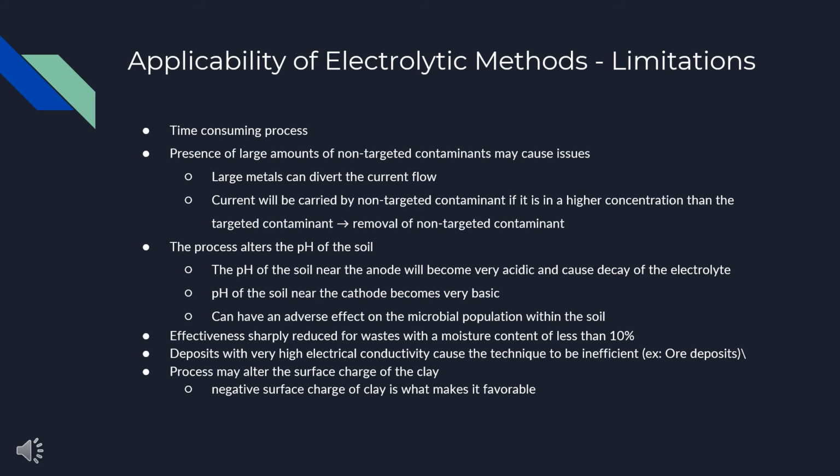Deposits in the ground, such as ore deposits, may have high electrical conductivity, again affecting the electrical field between the electrodes. Finally, this treatment method is particularly dependent on the surface charge of the clay particles being negative. If this is not the case, or if the charge of these particles is altered during treatment, electrolytic treatment may not be appropriate or applicable.